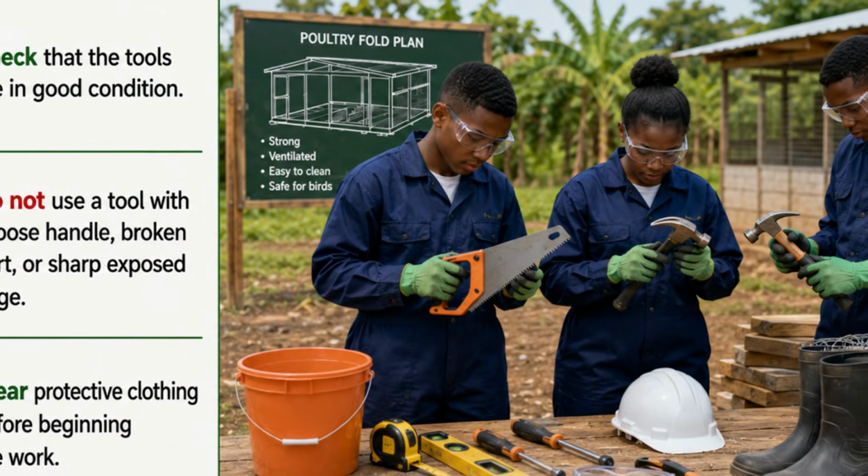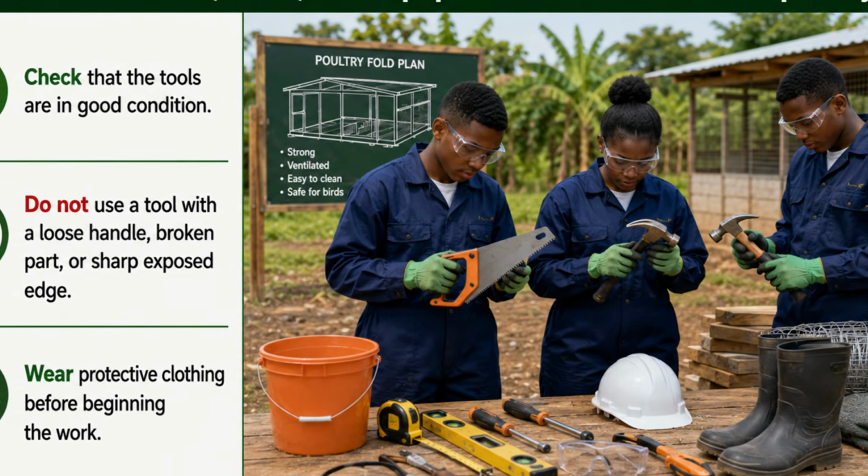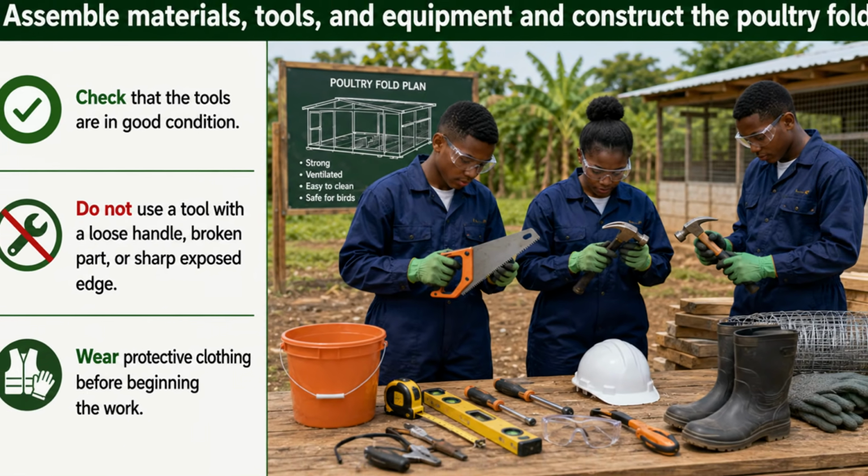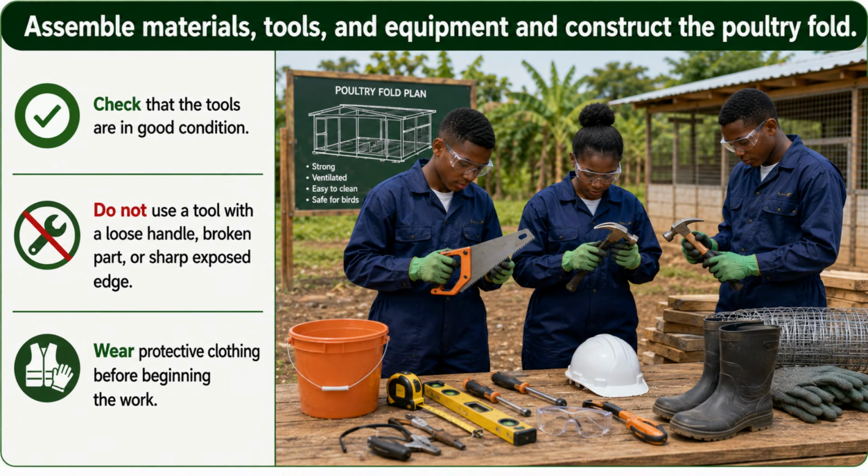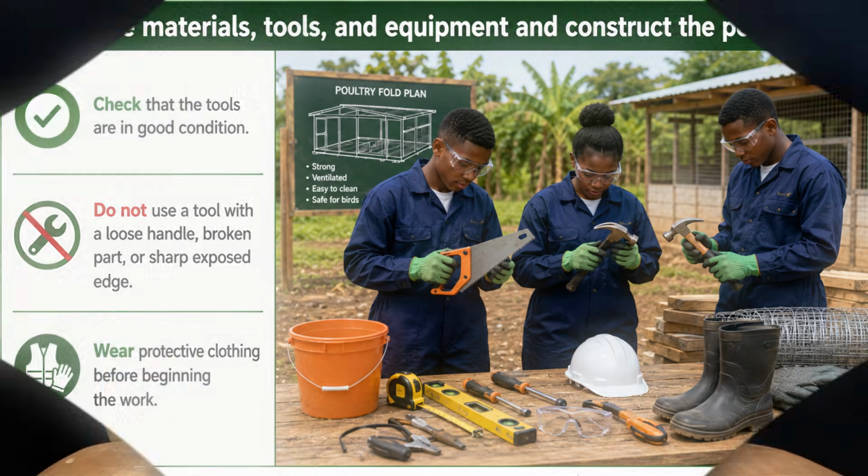And then once you have those materials, arrange them according to how they will be used. Check that the tools are in good condition, and do not use a tool with a loose handle, or one that is broken, and others that have sharp exposed edges. Make sure that they are safe to use. Then wear protective clothing before beginning the work.